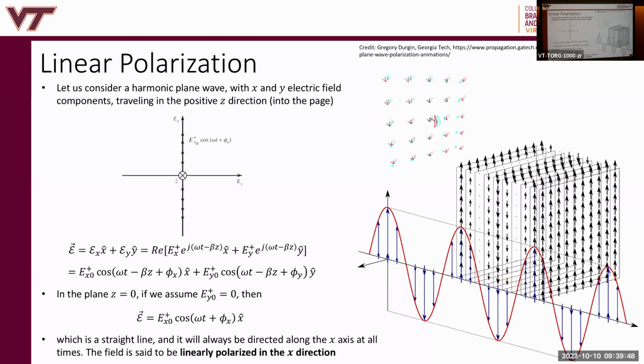And we looked at linear polarization, so I'll go through it kind of quickly. Remember also that this is E and H here. If you have two components, which was a requirement for CP that I mentioned before, and they're both the same amplitude, that's another checked box, but they're in phase. So if you add that electric field, the X and the Y, you'll just get a diagonal. And that diagonal will still trace a line in space. So they have to be 90 degrees out of phase to get CP.